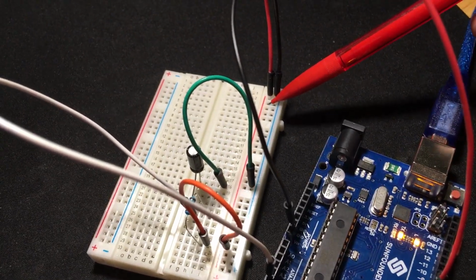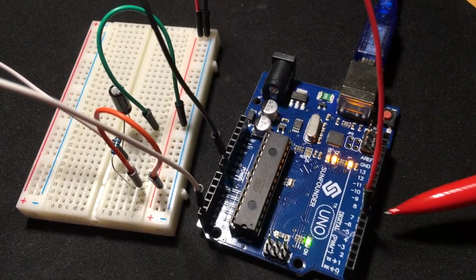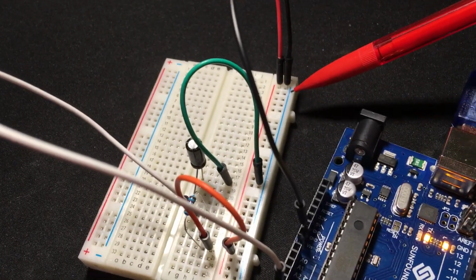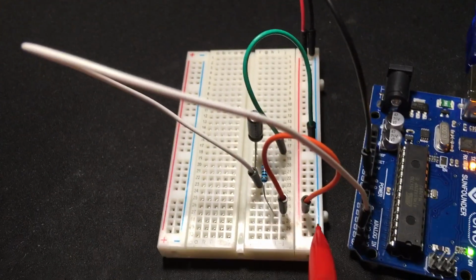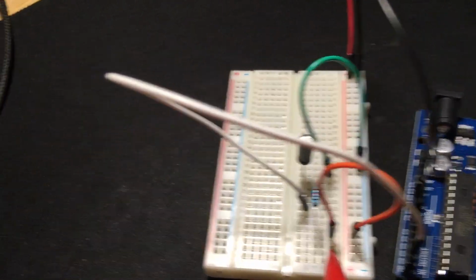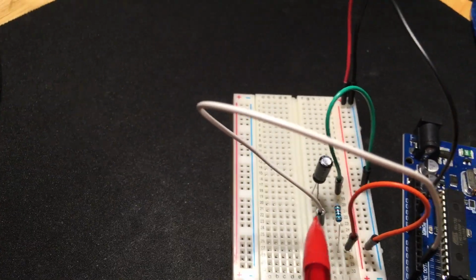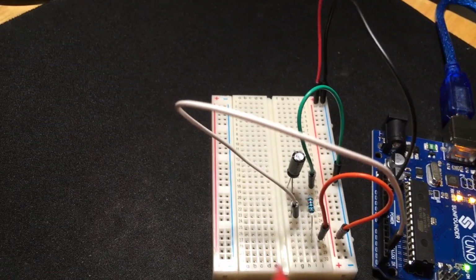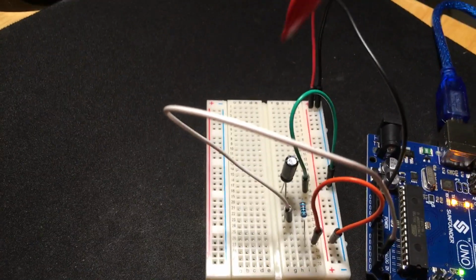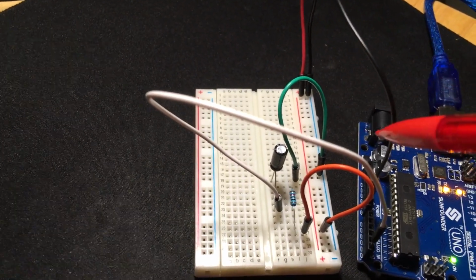The positive strip on the breadboard is connected to digital pin 7. The negative strip on the breadboard is connected to ground. The positive strip is then jumped to the resistor, goes through the resistor, and then in parallel goes through to analog in 5, as well as the capacitor. Once it goes through the capacitor, it is then jumped to ground.